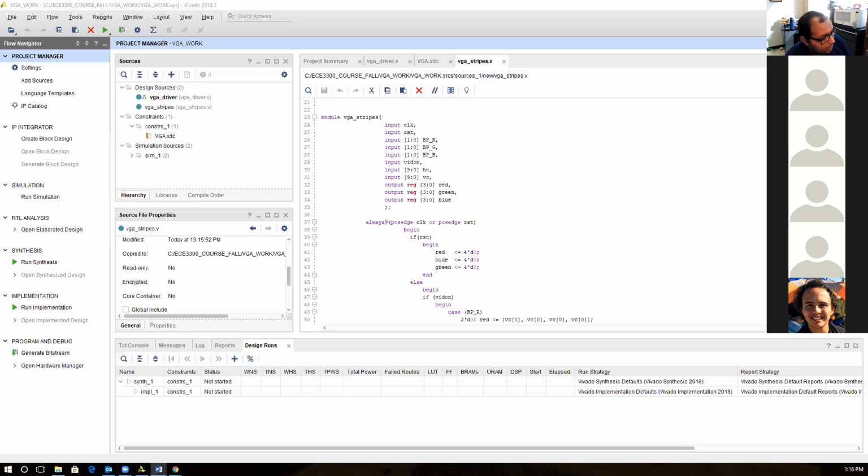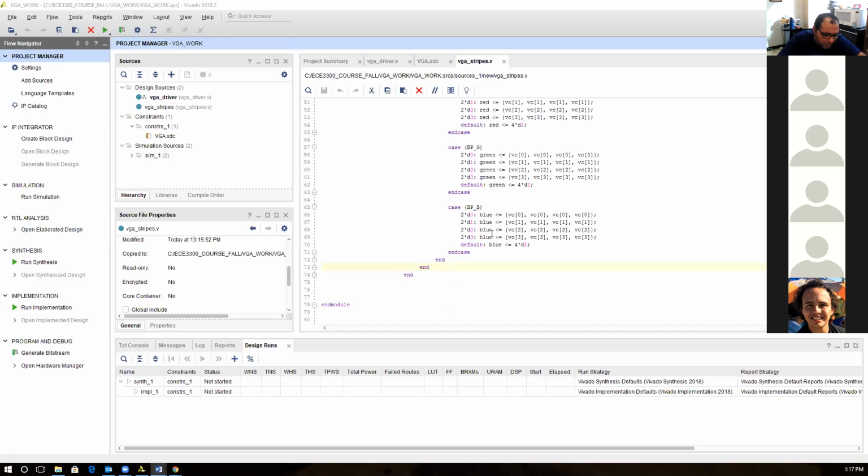You will draw it on the screen, you know what I'm saying? So you are sending something raw, and you will send it through the FIFO. And then when you pick the data out of the FIFO, you know it's a 56, and 56 has a meaning as a character, and you know from ASCII it means something. So you make another table, a case statement: if it's 56, draw this for him; if it's whatever, draw this for him. You understand what I'm saying? This is one of the very simple, naive ways of doing such a thing. Okay.